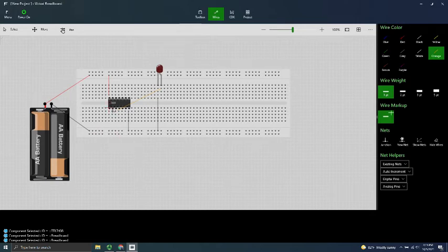We said 1 and 2 are inputs. So if you remember from the lecture from digital circuits, you need 2 highs with an AND gate to get the high output. So in other words, in order for us to get like a 5-volt out to get this LED to turn on, I need a high here and a high there to activate that circuit. So let's go ahead and show you 2 different scenarios here.